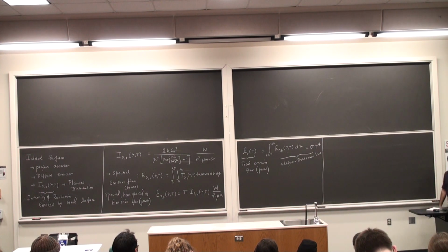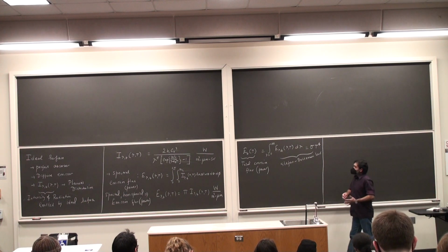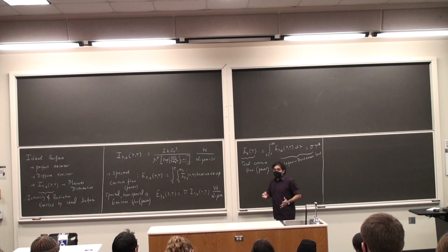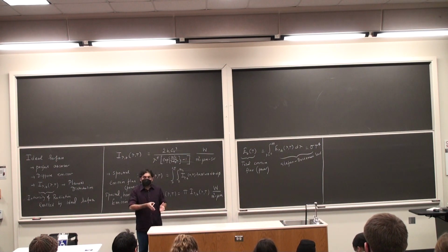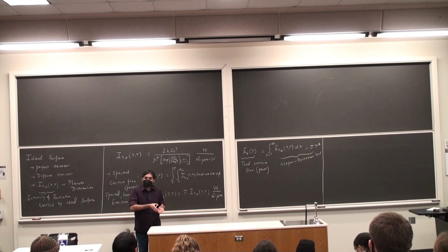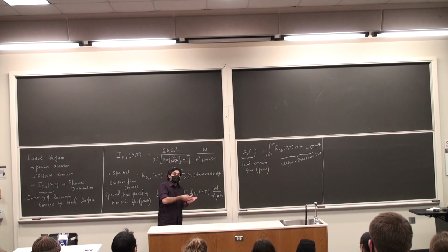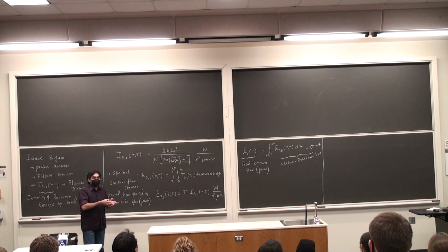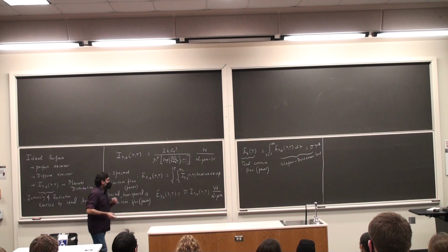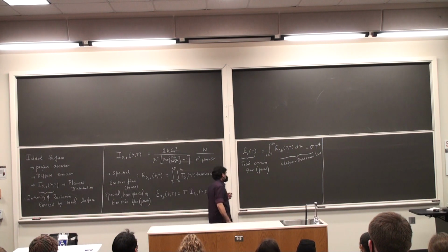And once again, mind you, this is for an ideal surface, which means that a real surface is going to emit radiant energy that is a fraction of the ideal surface. If I can somehow find out that fraction from experiments, if I can make use of the benchmark of an ideal surface from Planck distribution, then I can find the emissive power of a real surface. That is what we are going to be doing, okay? But before that, a couple of plots.